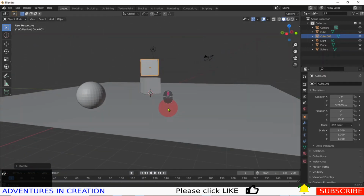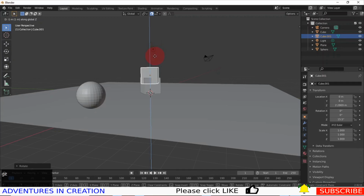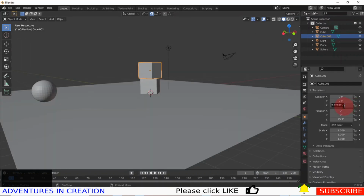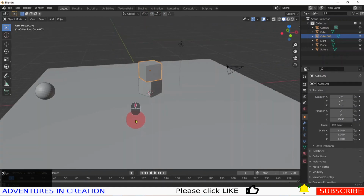so they're not dead straight. I'm going to turn on my magnet again and I'm going to move it down and settle it on top of that guy. Wait, that's not right. I see what it's doing. It's trying to take that center point and put it on the top. So now it is overlapping by a half. Well, I know these cubes are 1 meter high. So what I'm going to do is I can just type in 3. And now that cube's sitting dead on top. So there, everything is fine as it stands.